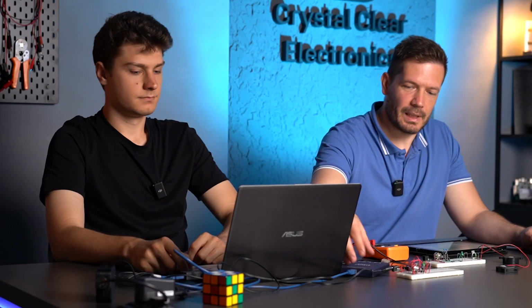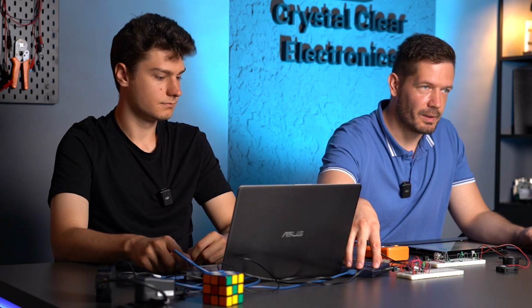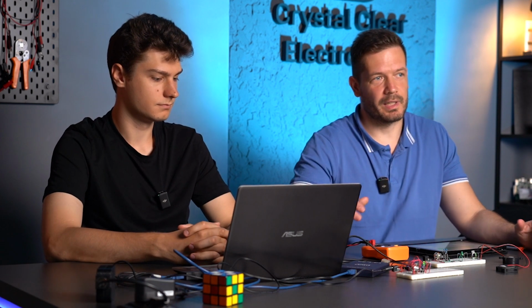My suggestion is to first examine what your circuit is doing exactly. First, check the output of the 555. To do this, as you can see, we've packed a laptop and a USB-connected oscilloscope. As you can see, this is a much smaller, more compact solution than the big box oscilloscope from the old days.